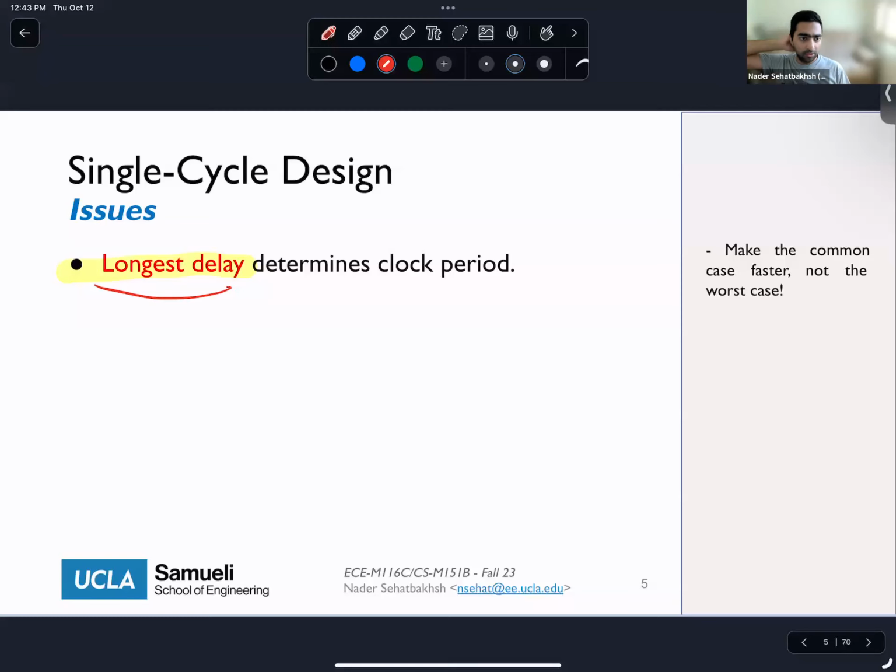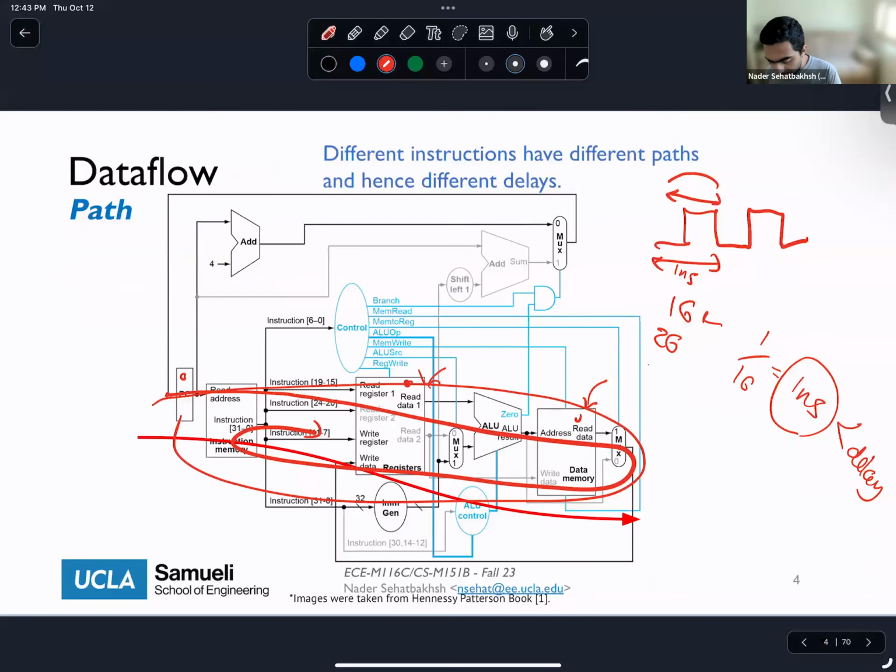There's a question in terms of the clock cycle you just mentioned. Does that mean you regularize every instruction so they all take the same time? No, they don't take the same time, but my clock cycle takes the same amount of time. So in reality, from the outside view, each instruction takes exactly 1 cycle. In other words, no matter how fast each instruction finishes, if I want to measure the performance, each instruction takes 1 nanosecond, okay? Why? Because my clock cycle is 1 nanosecond, right?